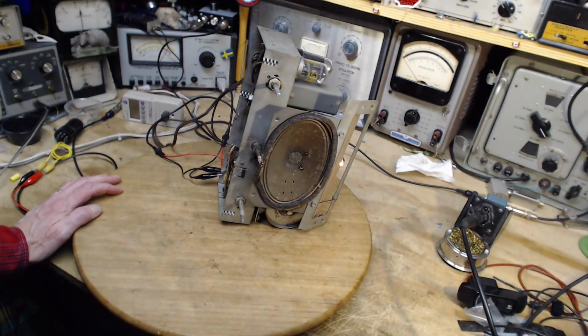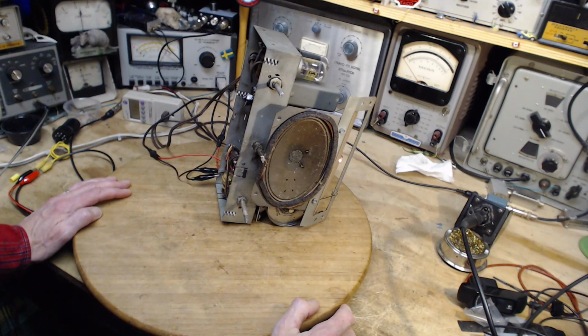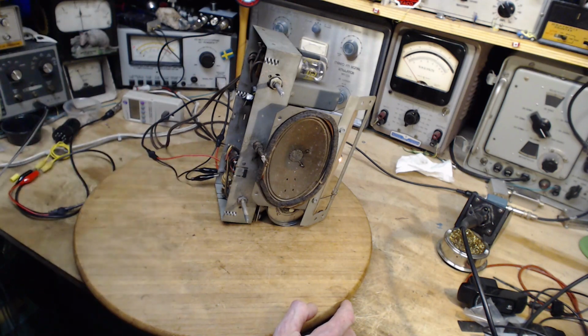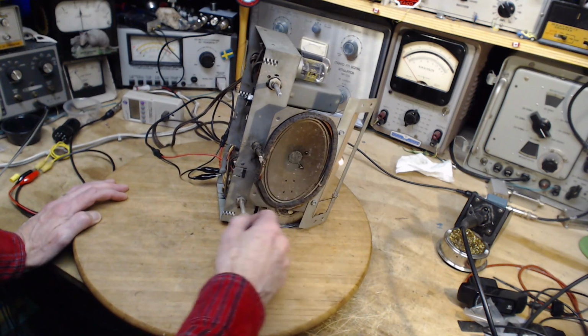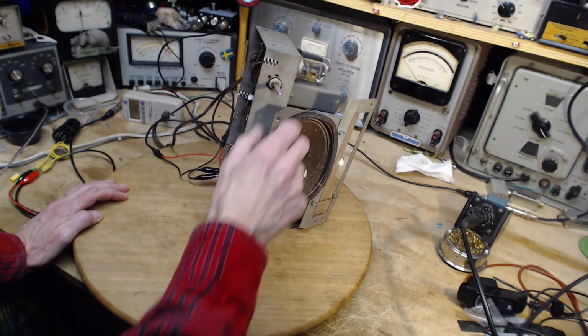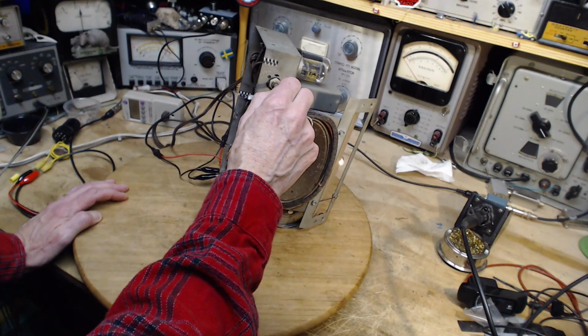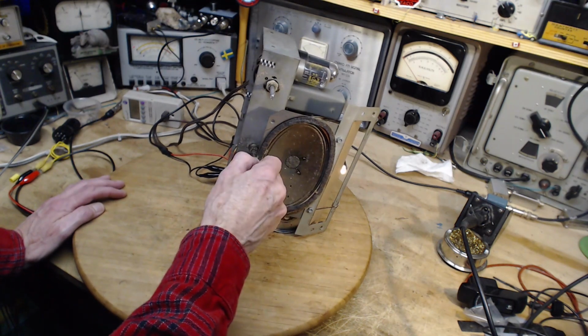Now the radio is connected to a good outdoor antenna, so it's going to operate. It's missing its own loop antenna. That's a lost thing. Like a lot of these radios, they have the antenna on the back. The back gets lost, and the antenna goes with it. People don't understand that the antenna on the back of the radio is part of the tuned circuitry of the radio, and so it's a big loss. Let's see what we can get here.